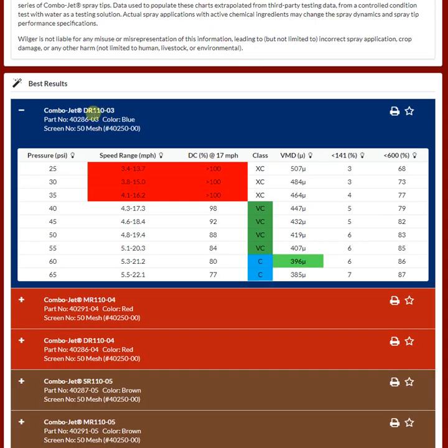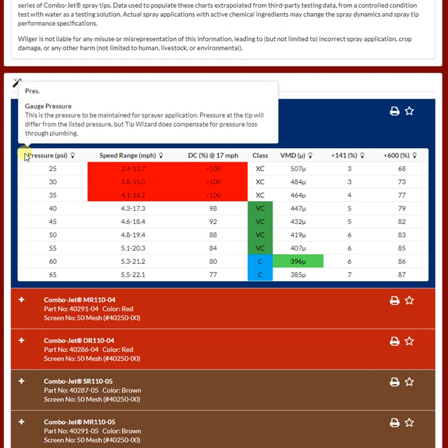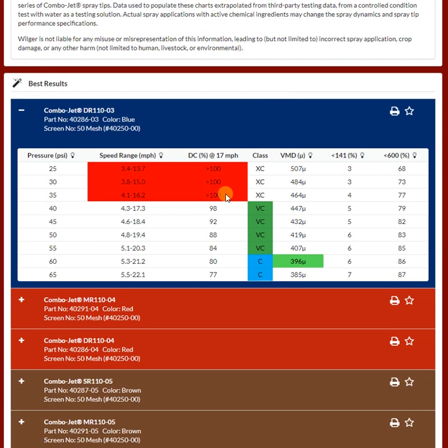We'll start at the beginning here just to make sure we're sizing our nozzle appropriately. With the nozzle size, it is important, but not the most important part of the spray application. We just want to make sure that nozzle size is going to be able to give us the rate that we need for pretty much the intended application pressure that we'd like to run at.